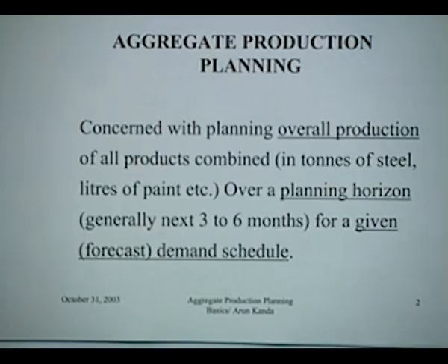So, the whole process in aggregate production planning is essentially to determine the aggregate forecast first. So, you do a process of aggregation, do aggregate production planning. Once you have done it, you will have to disaggregate it to obtain the individual pattern of demands, or rather production levels for individual products in that sense. So, I think this perception of aggregate production planning must be kept in mind.